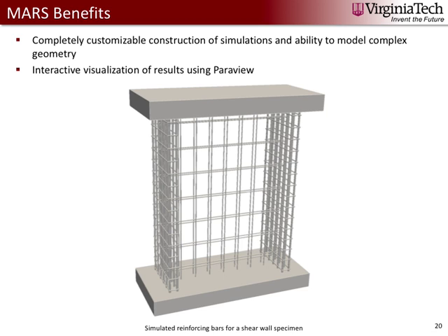Mars gives us the benefits of completely customizable construction of our simulations, meaning that we can have any sort of geometry of the members and rebars and so on, and apply any sort of loading or restraint conditions that we want. It also gives us the ability to have interactive visualization of the results using ParaView, which is a separate, freely available program. This image shows one of the capabilities of using the LDPM and Mars. We've simulated all the reinforcing bars for an experimental shear wall specimen. So it goes to show you that you can simulate the exact reinforcing bars and all the other aspects of tests.